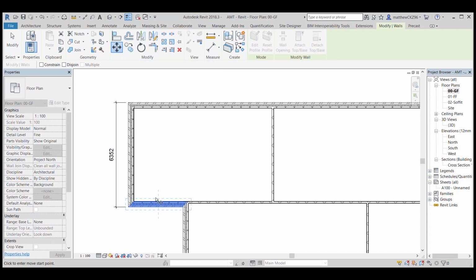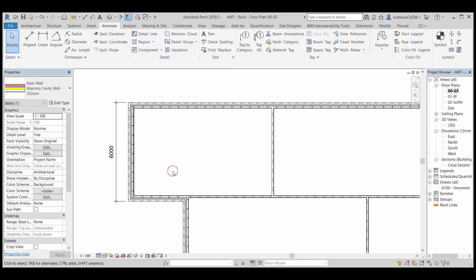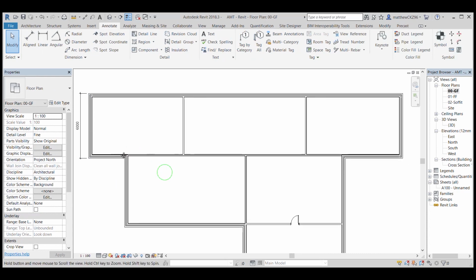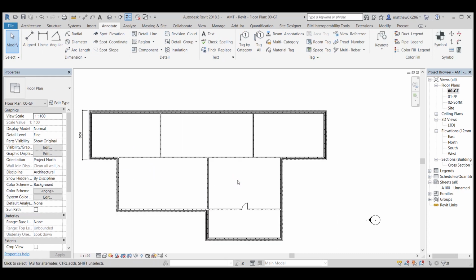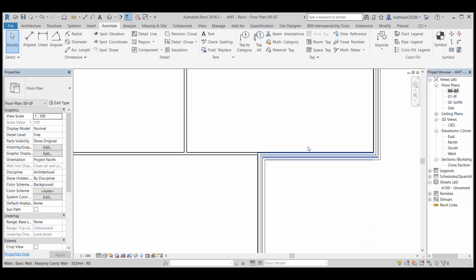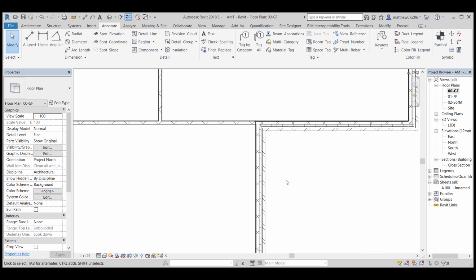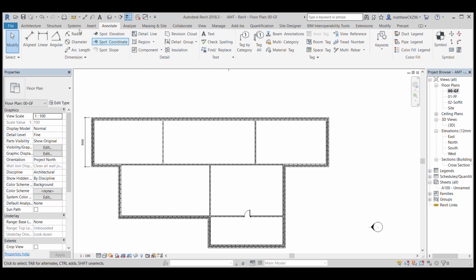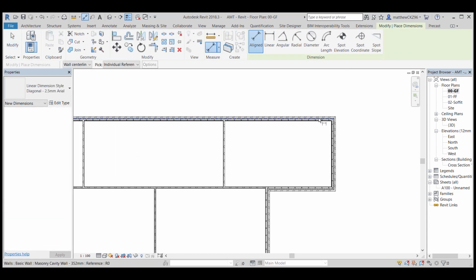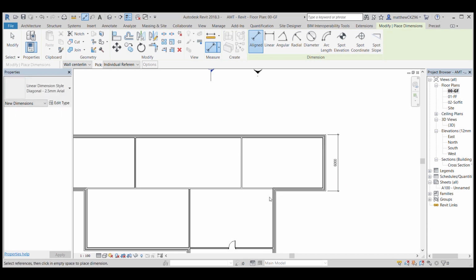and click the move tool and move it up 352. Now we have a nice round number. You notice it's moved this wall with it because it's joined, and it's probably moved this wall with it because it's joined as well. Go ahead and check that. Aligned, hover over wall, tab, blue line, hover over wall, tab, blue line. It has. There we are. Because they're joined.